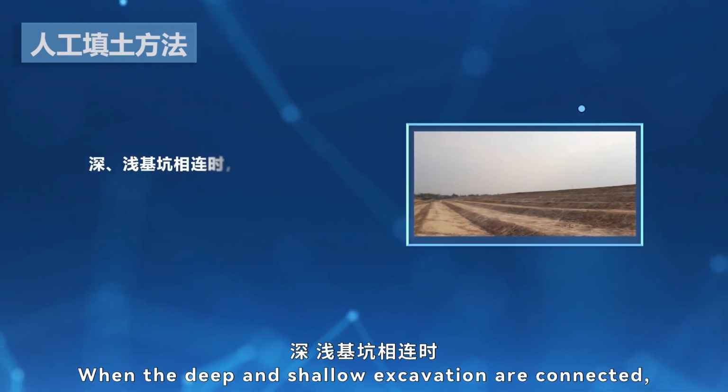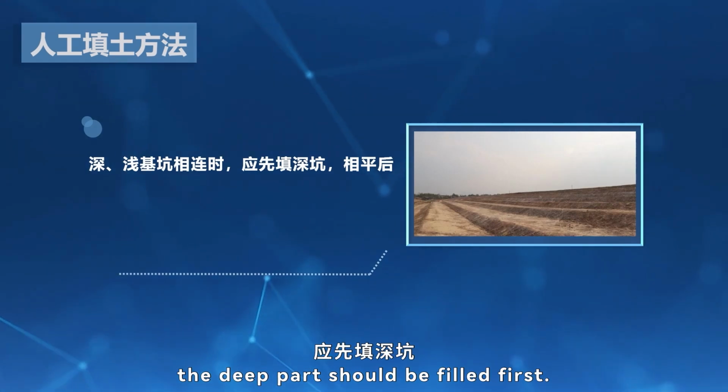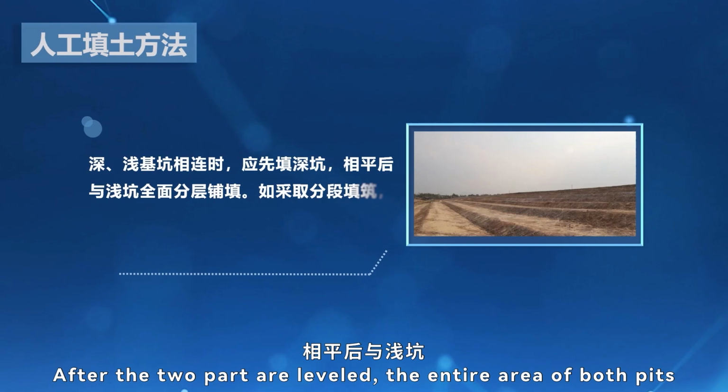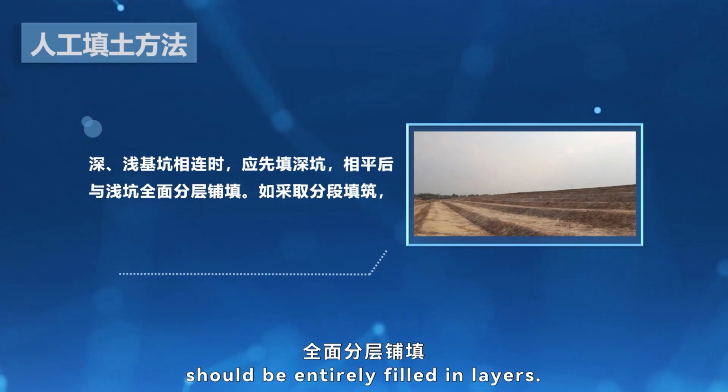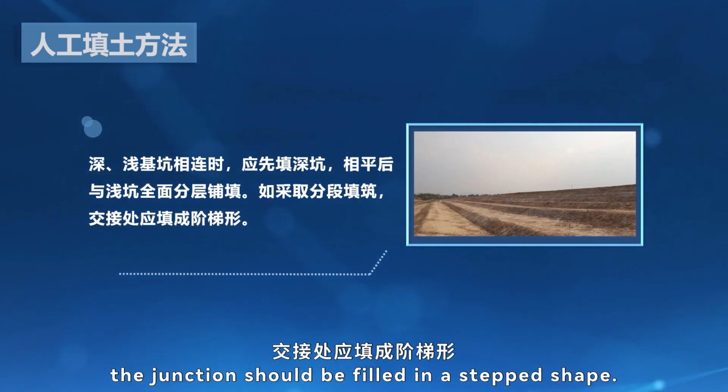When the deep and shallow excavation are connected, the deep part should be filled first. After the two parts are leveled, the entire area of both pits should be filled in layers. If we adopt sectional filling, the junction should be filled in a stepped shape.